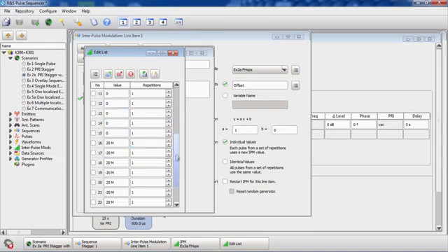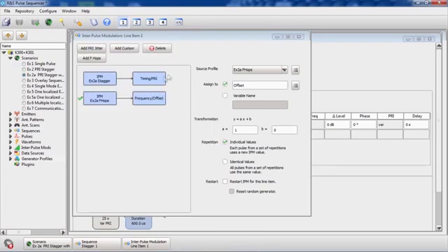And at the end, there are 10 pulses where I'm alternating the frequency offset with plus minus 20 MHz, which you can see here. The frequency hop works on the frequency offset. The stagger works on the PRI parameter.